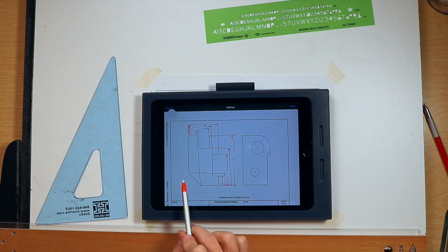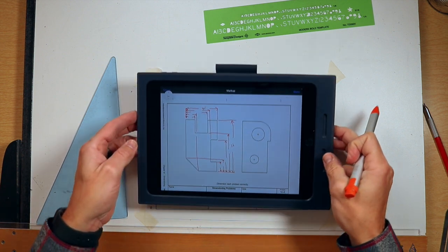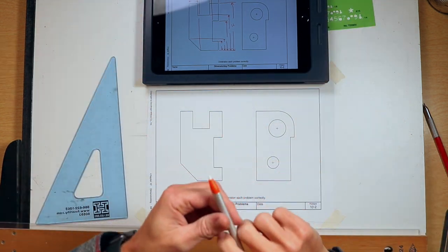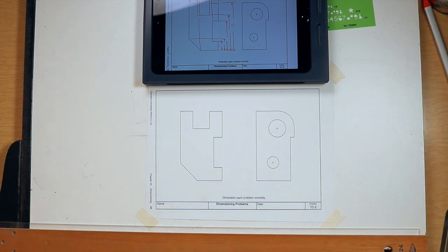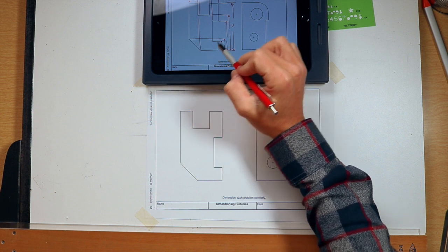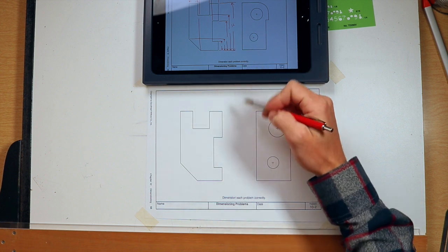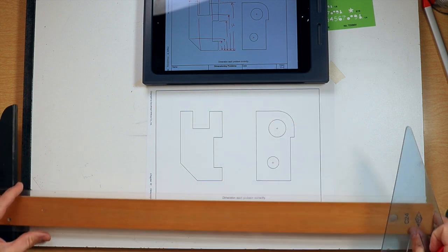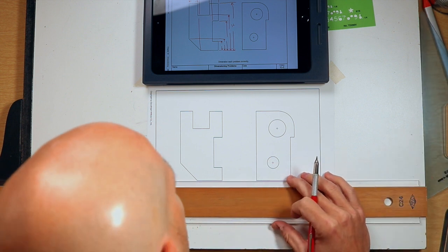If I want to put the height of the angle right next to the angle, that would be fine, and it would also leave me a little bit of room as I put in these other dimensions. Now that I have that, I'll put this up here, and I'm going to start my actual drawing. So I know that I'm going to go ahead and move the angle to this side. So I need, without that one there, 1, 2, 3, 4 height dimensions. So I'm going to extend off of the bottom edge.